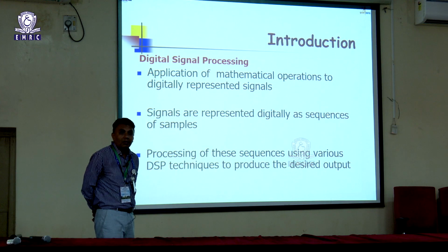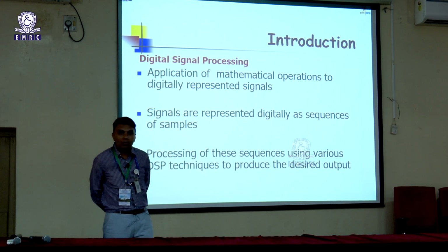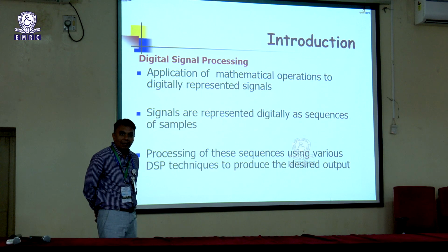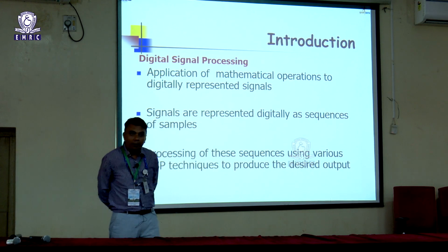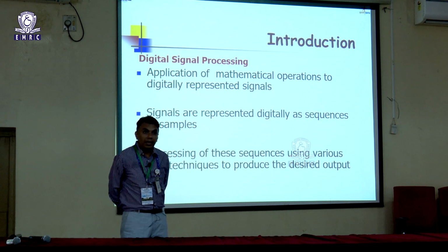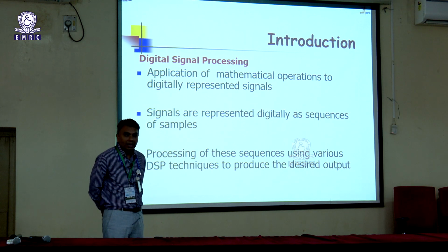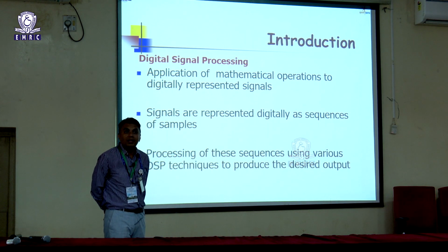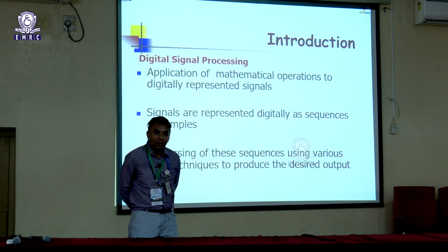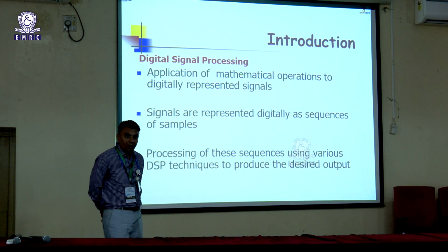Although we preferred soft processor because then our design is quite simple. But suppose we put the DSP processor with the FPGA, then synchronization of both the ICs and all the control logics has to be handled. So then it's slightly complex in design, and the thumb rule for the onboard design is your design should be as simple as possible.